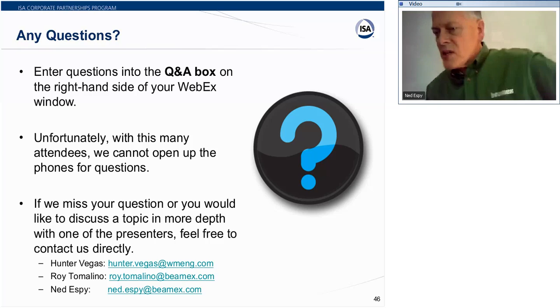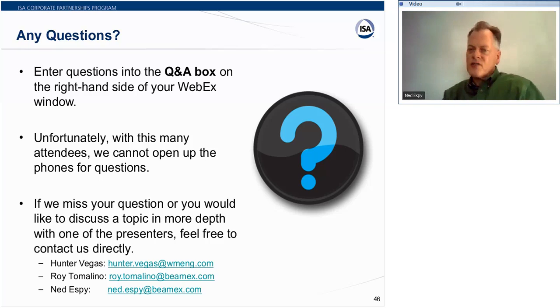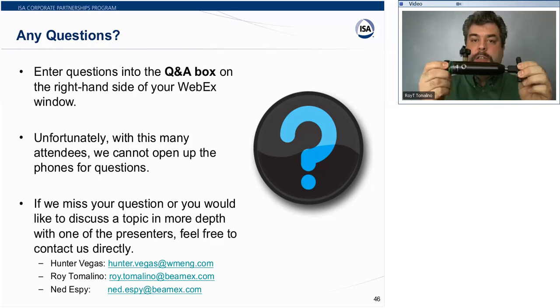Yeah, I was going to say BMEX makes a vacuum pump, and there are others out there. We can pull about 28 inches of mercury, which is probably like 350 inches of water on the negative side. I've got that right here. I just didn't need to use it for this small vacuum amount.